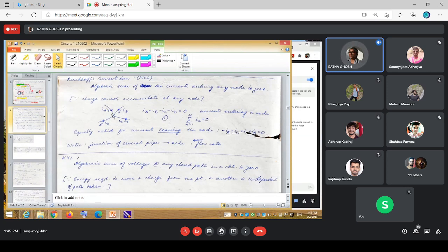This is for the power absorbed convention. Had it been the power delivered convention, then obviously these you would have treated as minuses, and these as pluses. So the overall equation would just be multiplied by a minus sign. You would have minus IA minus IB plus IC plus ID is equal to 0, and that would still be the same relation. IA plus IB would still be equal to IC plus ID.